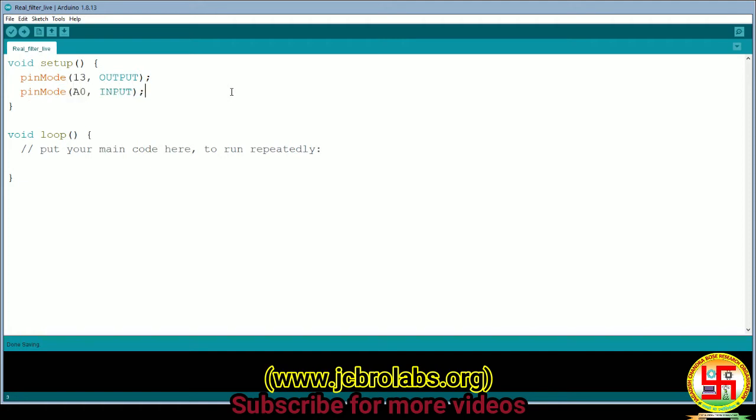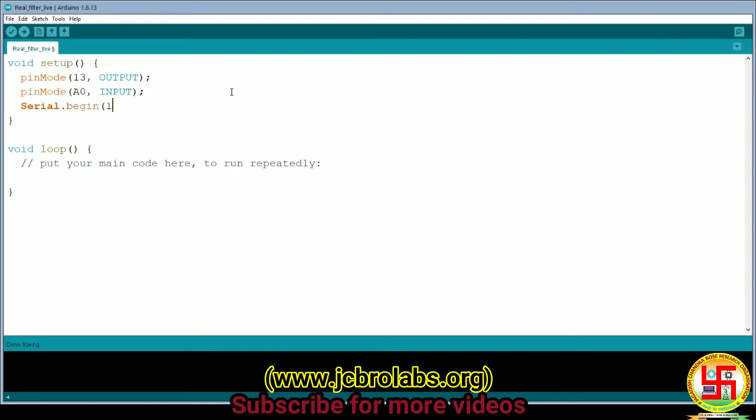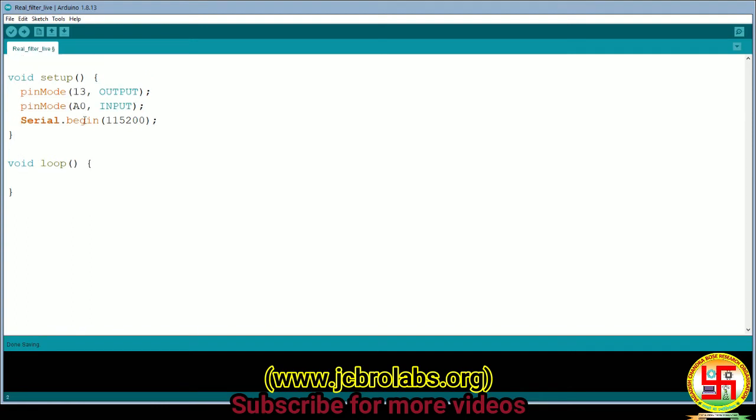Okay, we'll save it, and then we will send the data to serial port as well. So Serial.begin with 115200. Okay, now, because right now what we want to do, we want to acquire the data, and we want to see what sampling frequency we are getting.